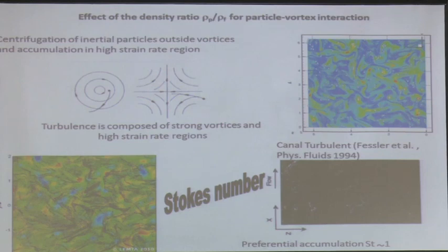And then the particle concentration is also evenly distributed. But in between, when the Stokes number is of order 1, 2, 3, you see this preferential accumulation when the Stokes number is of order 1. And it's very important because it may have some effect. So you were asking me about the effect on possible mass transfer, chemical reaction.